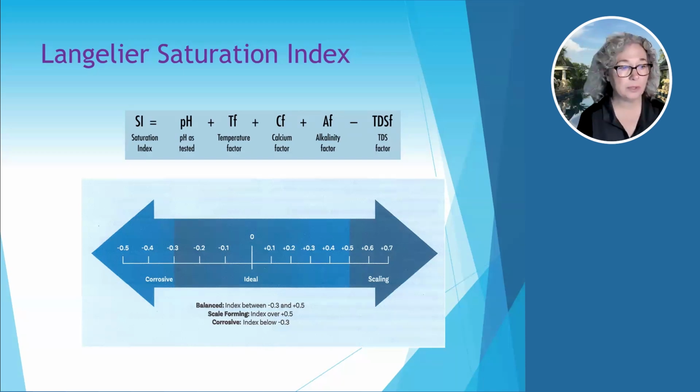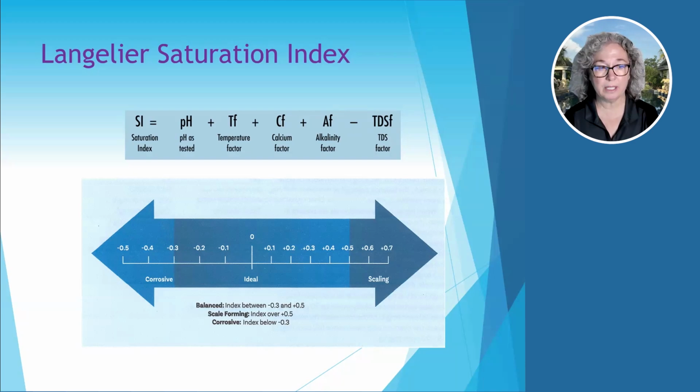If you notice, the saturation index is the pH, temperature factor, calcium hardness, and alkalinity factor, and you take away the total dissolved solids. This is what a balanced pool is.